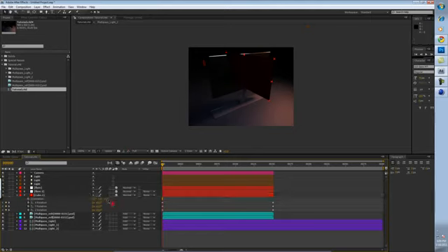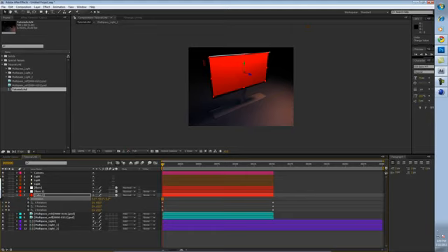Then I can rotate it in what axis? Not the z-axis. I believe the x-axis. Nope. Y-axis 90. So if I do 90 degrees in the y-axis, then I get my solid placed on my screen.